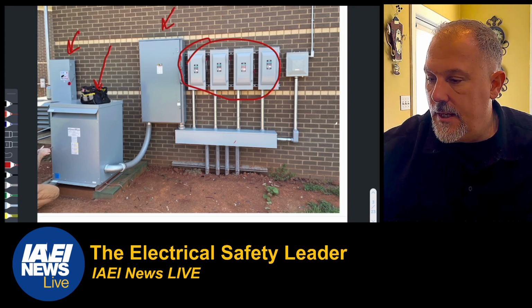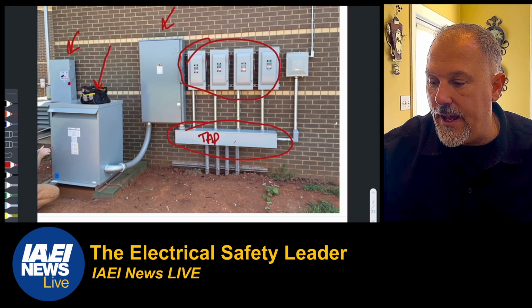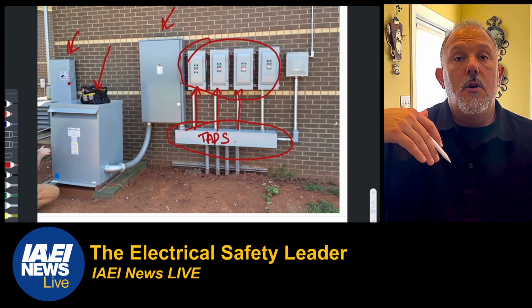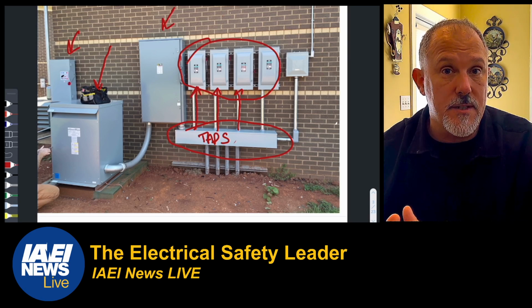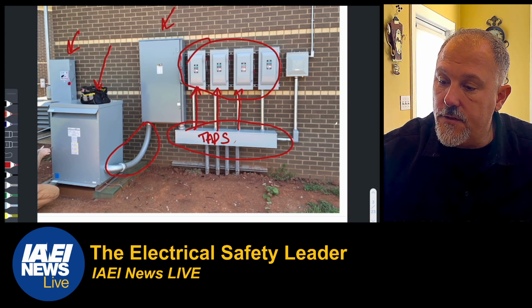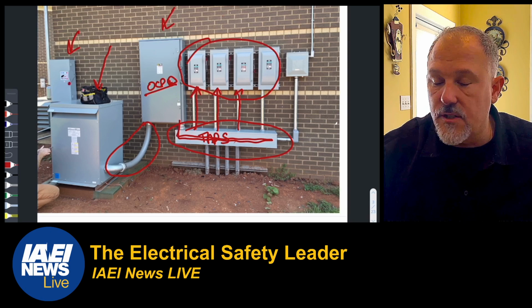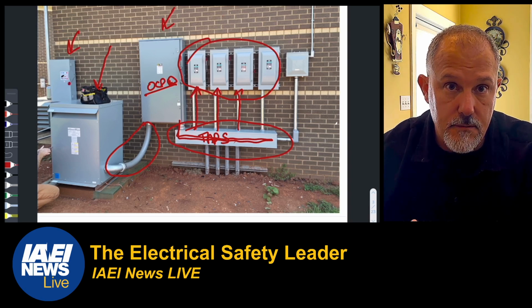All right, so what I want to do is focus on this here. This is where you would have your taps. The conductor from that going up to this switch would be your tap conductor. The reason this is a tap conductor, and not a transformer secondary conductor, is that this is a transformer secondary conductor, which serves an overcurrent protective device, OCPD, which protects a feeder, right? So there's a feeder, and then off of the feeder are tapped conductors. So these are feeder taps.